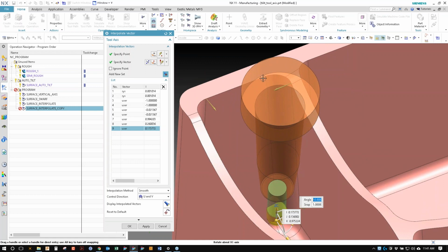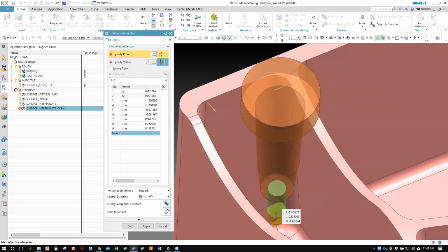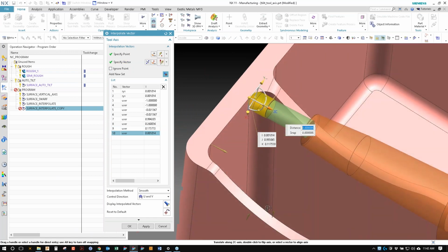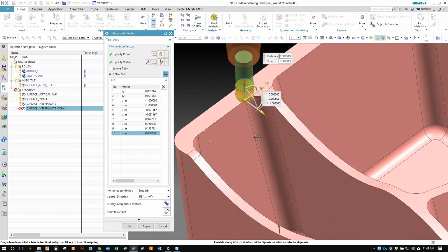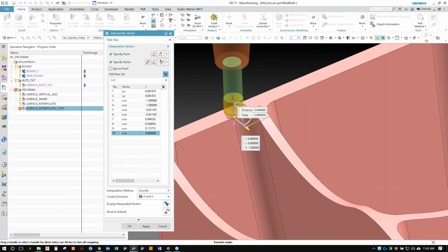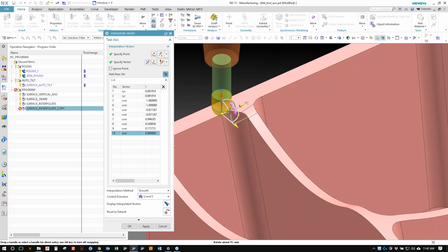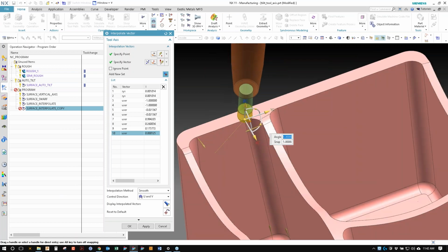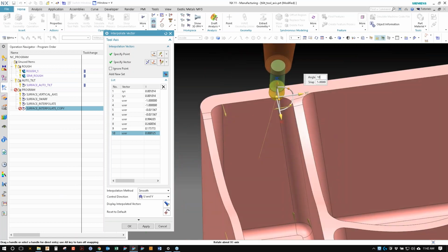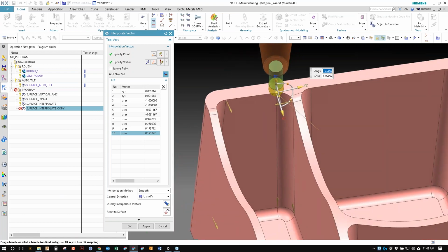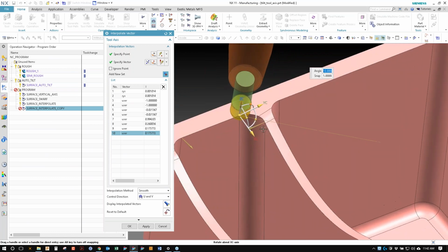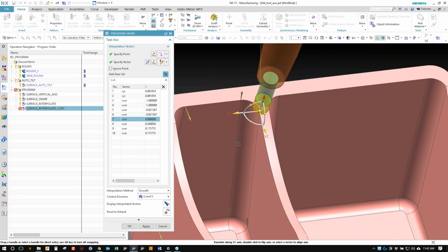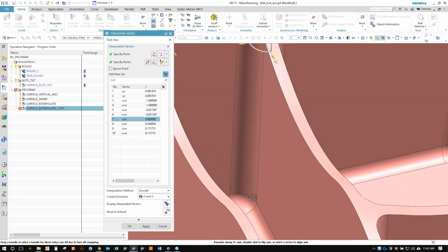So we don't have one up here at this endpoint, so I'll add another one. We'll add there, start with it normal to the floor, and then F3 will get rid of those dialogues, start to tilt it. So we'll say 8 degrees and 10 away from the wall. And then it's important, one more here. So this one I'm going to leave for a moment and jump down here.